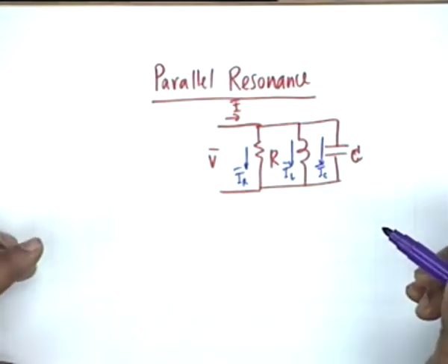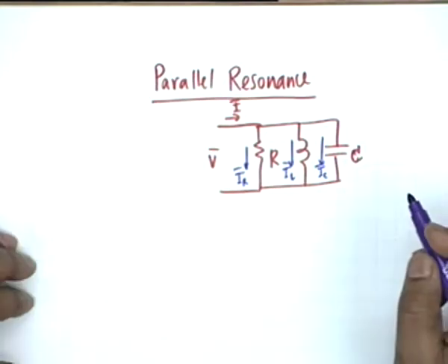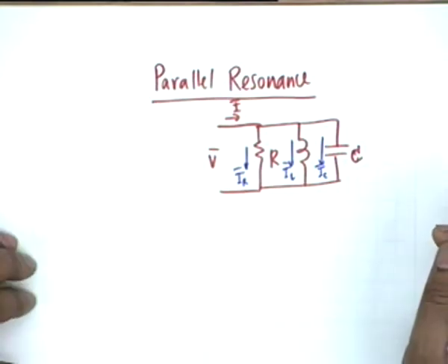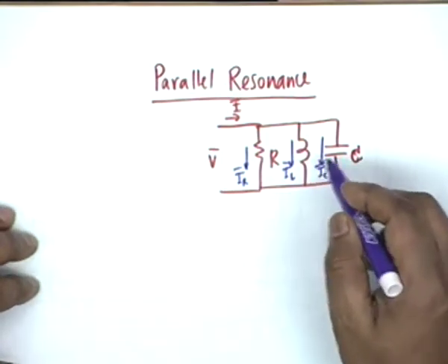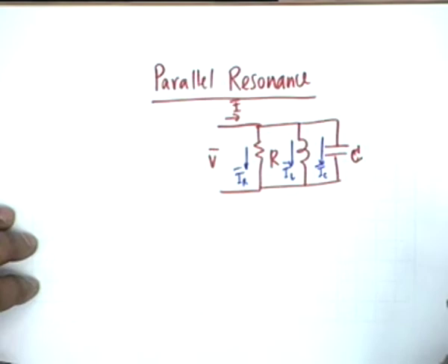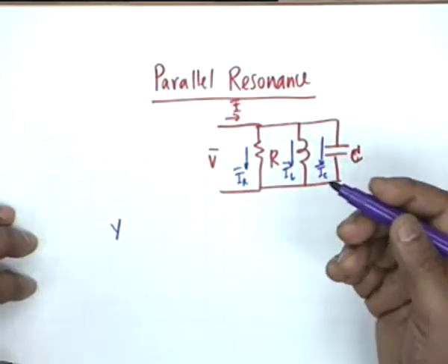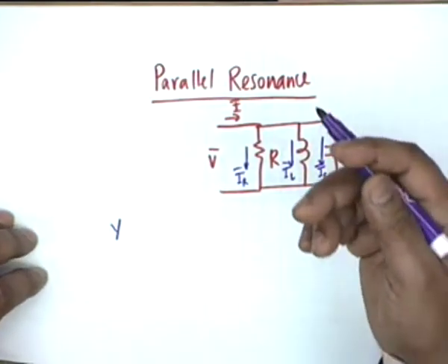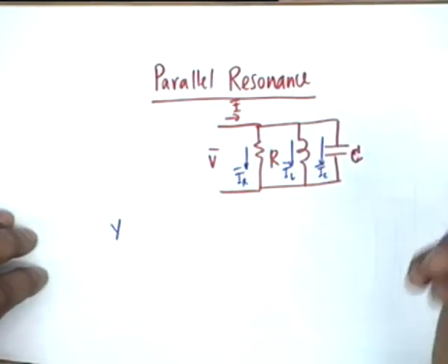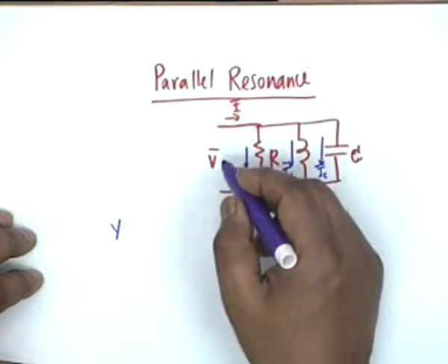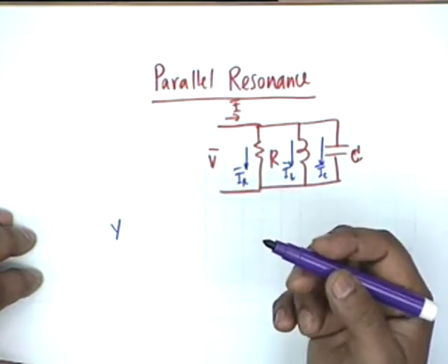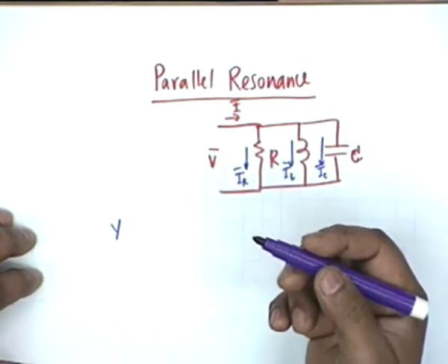They are not in series now, and therefore what can be cancelled? Not reactance but susceptance. Susceptance of the inductor shall be cancelled by the susceptance of the capacitor. Well, this can be formally proceeded with exactly in the same manner as we did for the series resonance circuit, but you can see that the most appropriate thing to compute here is the admittance. All right.